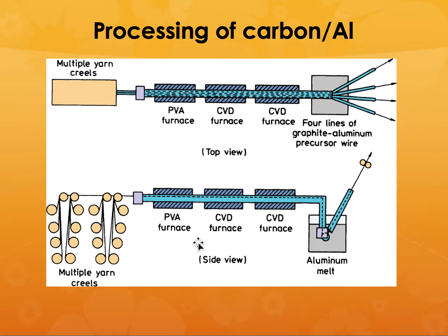If you're doing applications such as a ballistic impact type of application where you are using carbon fiber reinforcement in aluminum, you have to be very, very careful with this process because the carbon itself can result in a galvanic potential difference between the aluminum and the carbon itself. So it can initiate corrosion from those points. Or, for example, sometimes the carbon itself will get reacted with the aluminum when it is poured into the mold, and it can